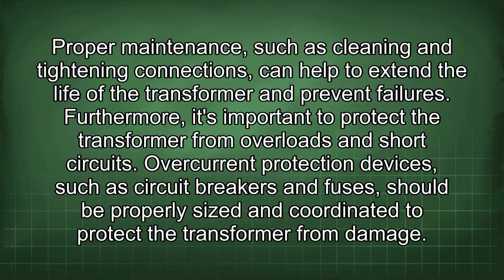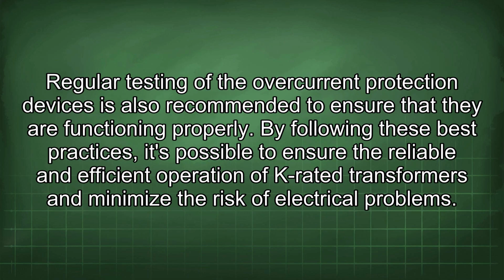Furthermore, it's important to protect the transformer from overloads and short circuits. Overcurrent protection devices, such as circuit breakers and fuses, should be properly sized and coordinated to protect the transformer from damage. Regular testing of the overcurrent protection devices is also recommended to ensure that they are functioning properly. By following these best practices, it's possible to ensure the reliable and efficient operation of K-rated transformers and minimize the